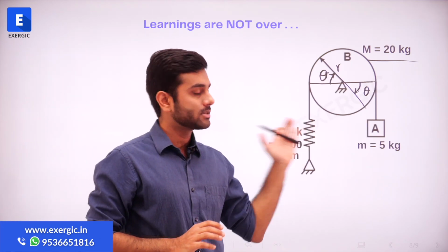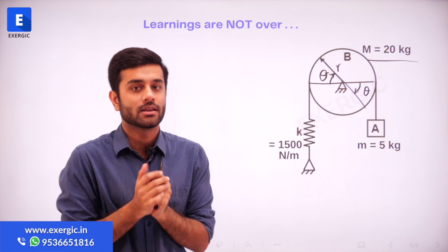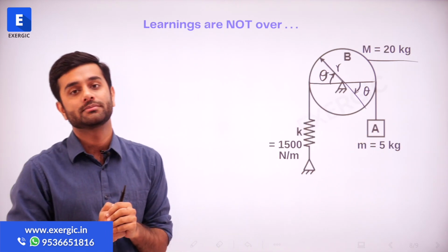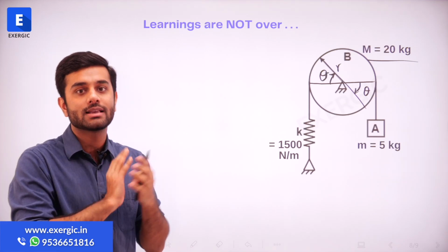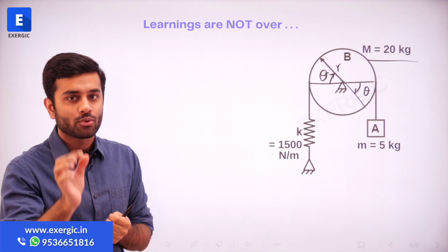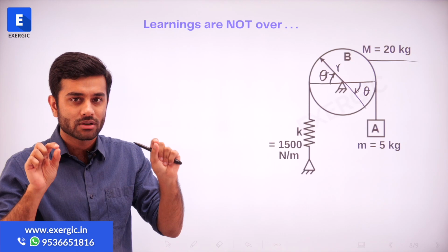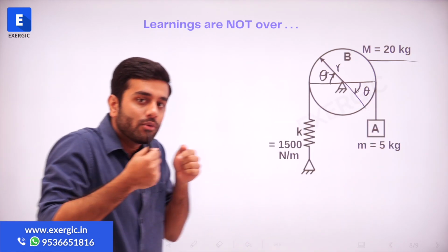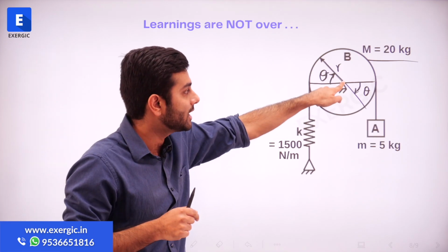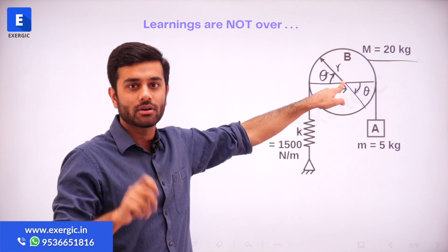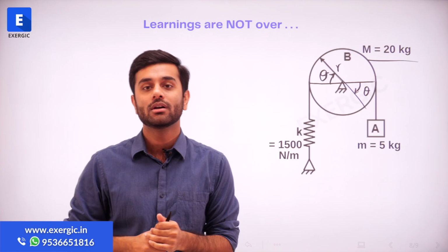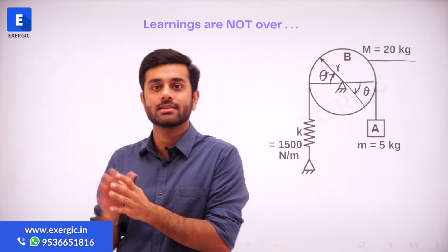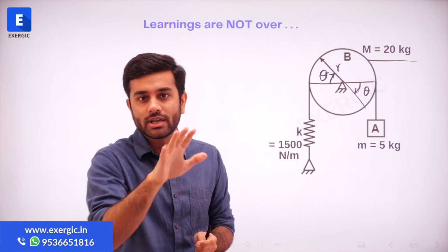Now, in this question, to write the equilibrium equation, you have two cases of linear motion and one case of rotational motion. So, how are you going to analyze the system? Obviously, we will take the rotational motion equation. We will try to write the equation for rotational motion. Why? Because these linear motions can be converted to rotational motions about the center point Q, right or not? If you have been given a rotational motion, to convert that into a linear motion requires some additional analysis which may not get you to the answer.